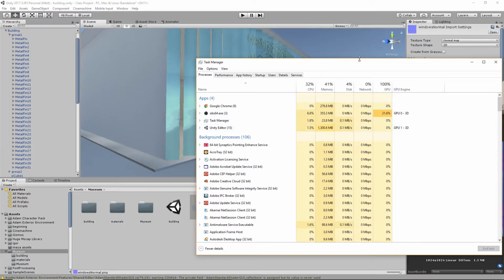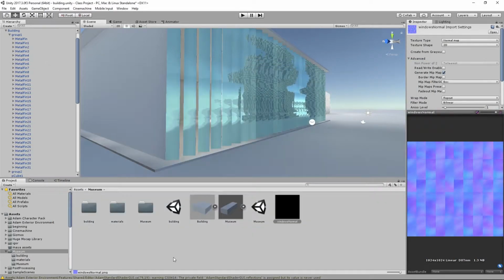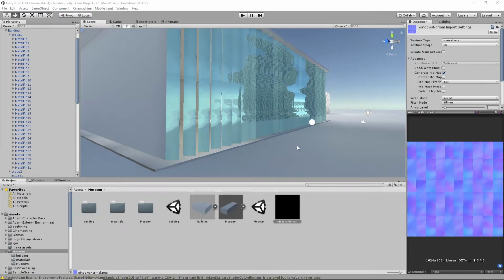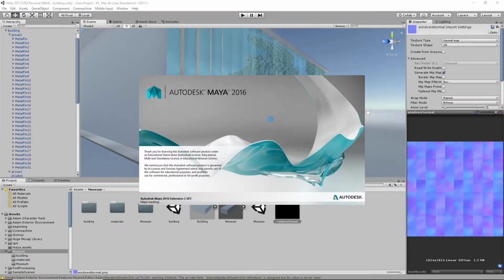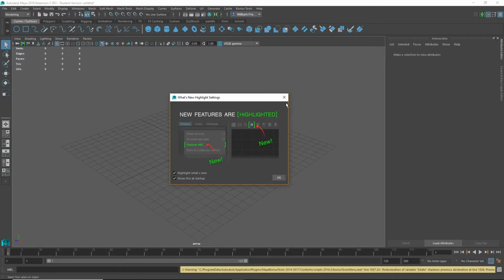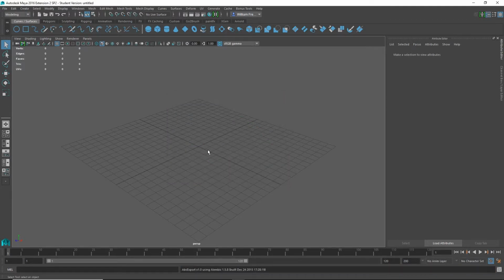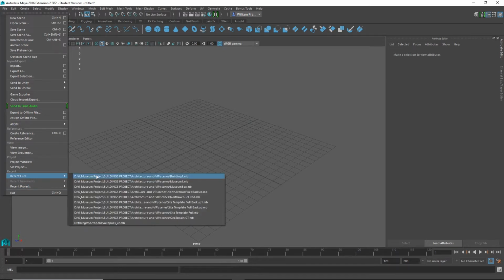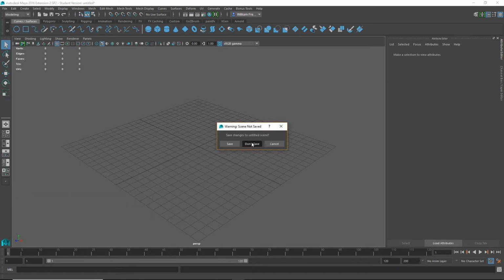All right. Now I'm going to start Maya back up. Try this again. I'll make sure I save as I go, do an automatic save so I don't have to, hopefully, and I can also delete by type history, which can also save it some. So file, let's open the recent, don't save.